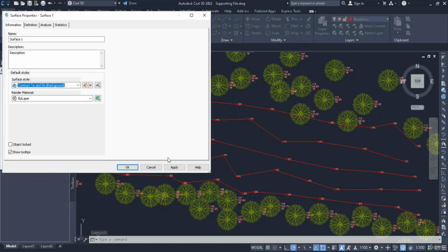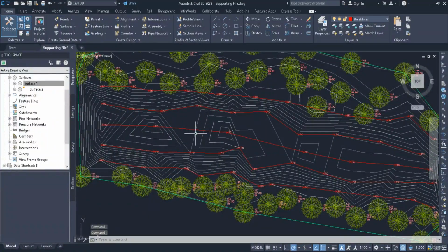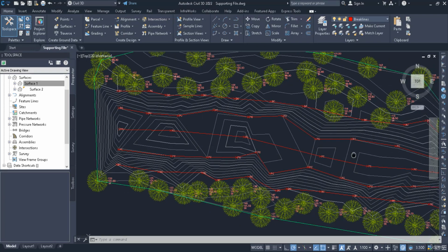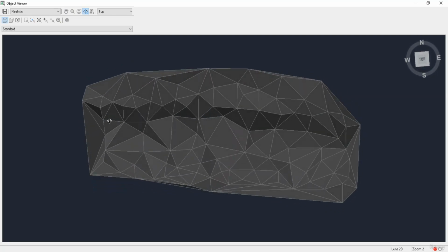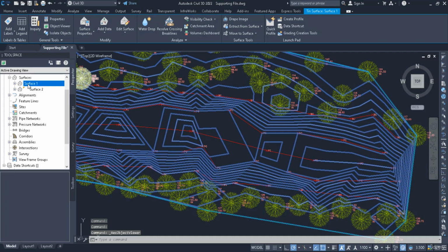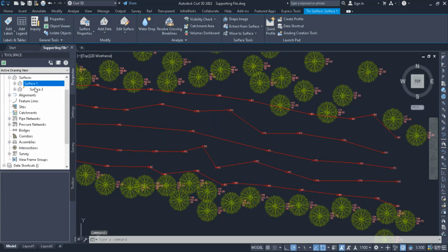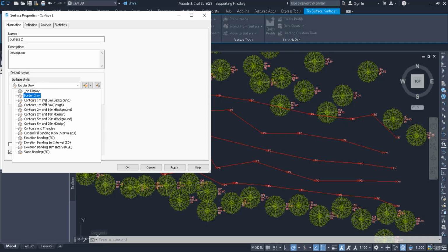First we will see surface 1. This was the surface 1. You can see these dark big patches. They are empty, and here we can assume that the information is incorrect. Let's see from this point. If we want to go quite near to what this surface would actually be, we have to use the surface with the break lines, and let's display it now.